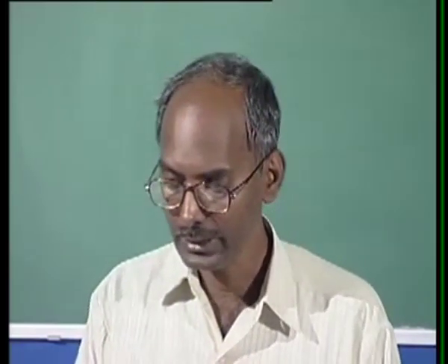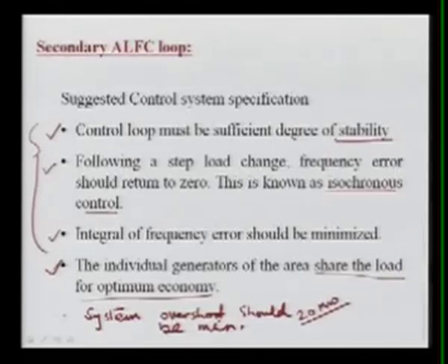Second is the need for frequency constancy. As we noted, if there is a change in the load, the frequency error should return to 0. And this is called isochronous. The term iso is basically used: iso means constant, and chronos means time, so it means constant time.